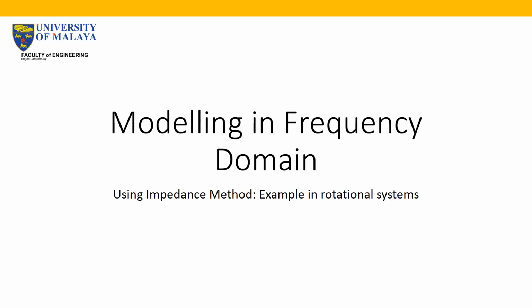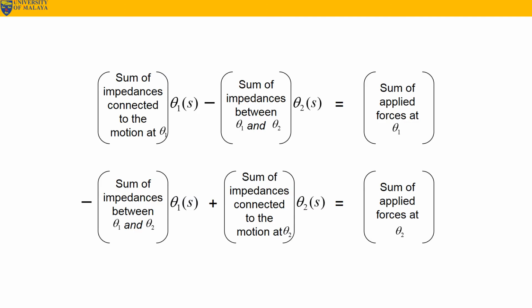In this video, I will go through the modeling of systems in the frequency domain using the impedance method, specifically for mechanical rotational systems. So for a rotational mechanical system, for a 2-degree of freedom system, this particular set of formulas is used in order to write the equations of motion using the impedance method.